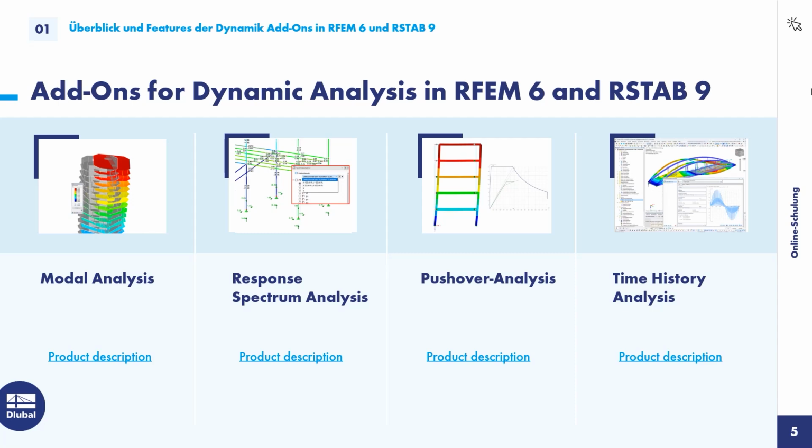The pushover analysis itself is mainly used for retrofitting structures. So imagine a structure built plenty of years ago, and it already endured an earthquake, and now you want to see where do I have to look for problematic beams which could have yielded or could have been destroyed during the earthquake.